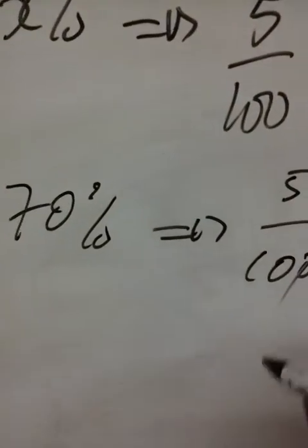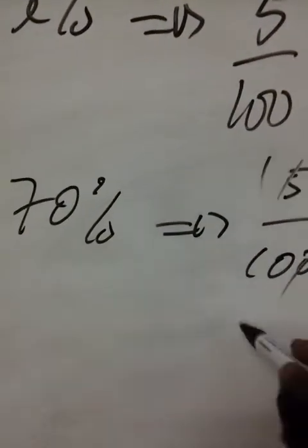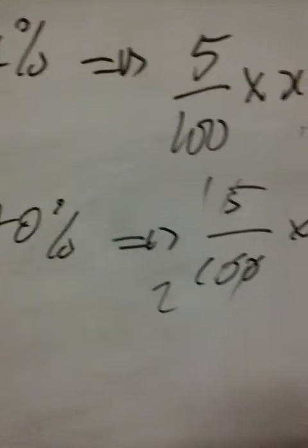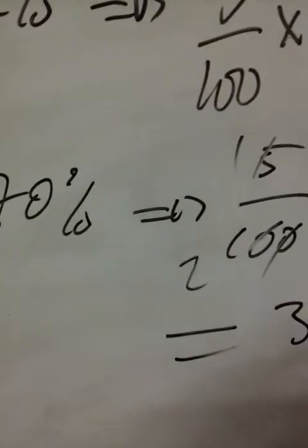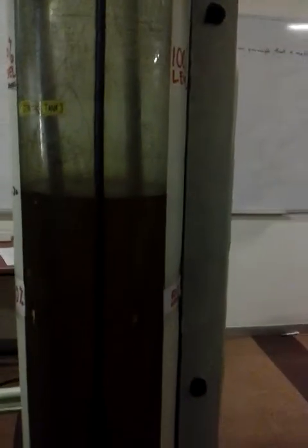That is 1, 2, isn't it? 1.5, 2. That means this is 3.5 volts. So if the level in this tank is at 70%, I'll be expecting an output from the sensor of 3.5 volts. Let's check that. Let's prove it.